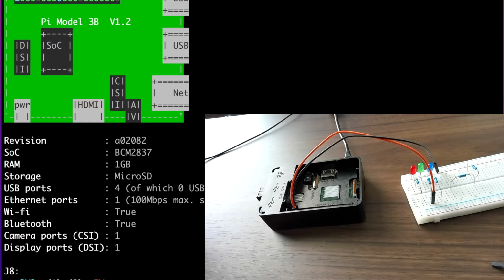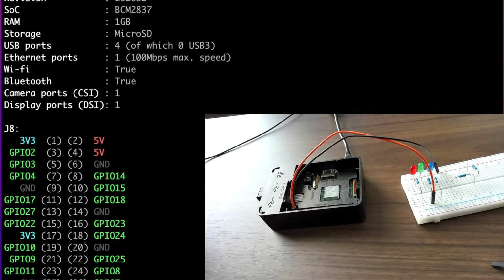Or otherwise, you can just reference the pins with their name. As I showed you in a previous video, each pin has a certain tag associated with it. If you decide to call them by their name, that means you are using GPIO.BCM. As you can see, physical pin 1 is 3 volt. Physical pin 3, if you are using GPIO.BCM, you can say GPIO2. This is what we are going to use throughout our programming.